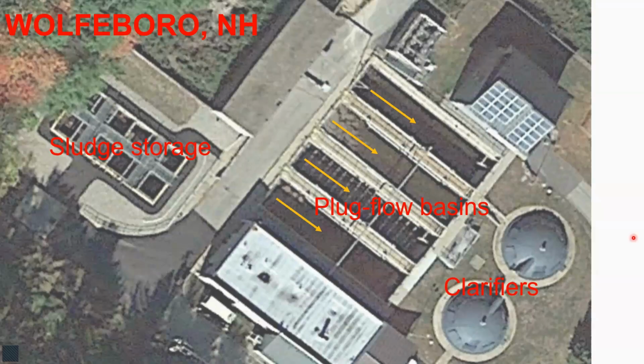This is a plant in Wolfboro, New Hampshire. Probably pronounced that wrong as well. It's an old plug flow extended aeration basin. Very well operated, well maintained. Pretty manual operations yet, as far as control of sludge blanket, return activated sludge, wasting. That tends to be pretty manual.